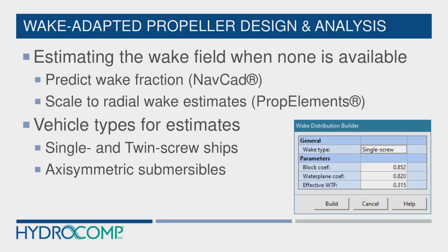Now, how do we estimate a wake field when none is available? Wake adapted propeller design is important for us to do as early in the design spiral as possible because it addresses key characteristics that are not necessarily fully modeled in our system calculations in a tool like NavCAD. We want to look at a little bit more about our unsteady calculations and our wake adapted performance. Also, we have the ability of using more contemporary foil sections in a wake adapted propeller tool.